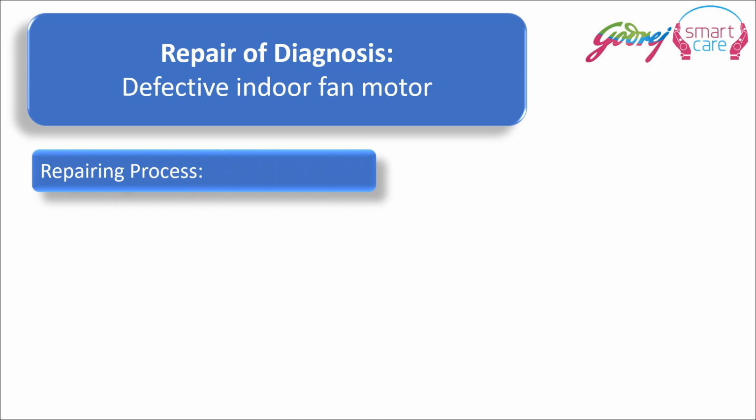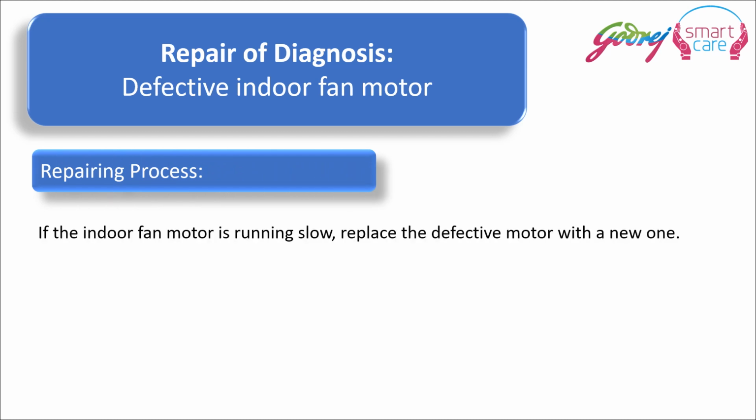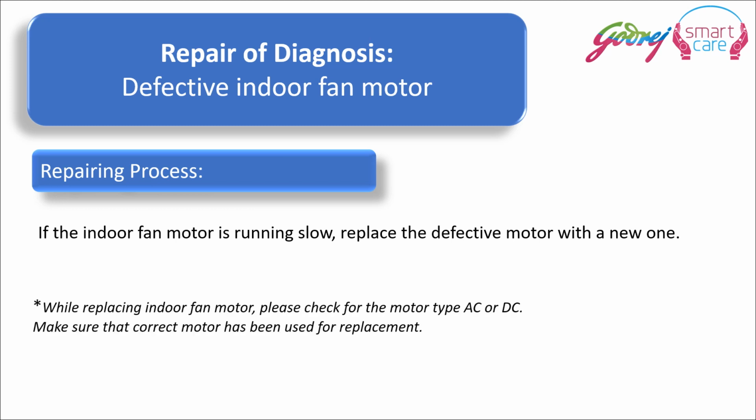Defective indoor fan motor: if the indoor fan motor is running slow, replace the defective motor with a new one. While replacing the indoor fan motor, please check the motor type, AC or DC. Make sure that the correct motor has been used for replacement.